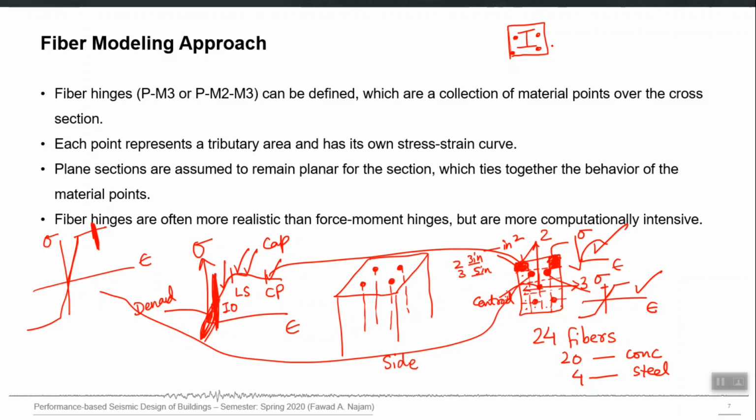For all those cases, with the plastic hinge modeling approach, you will not be able to get those modeling parameters and acceptance criteria values for plastic hinge modeling of those columns. So you have to come to the fiber modeling approach, because the beauty of this idea is, let's say that you have a steel section embedded.